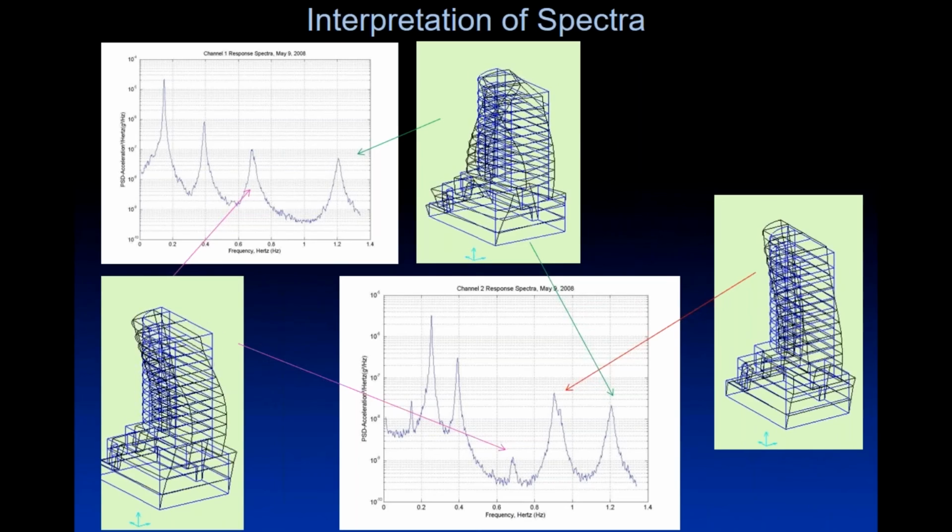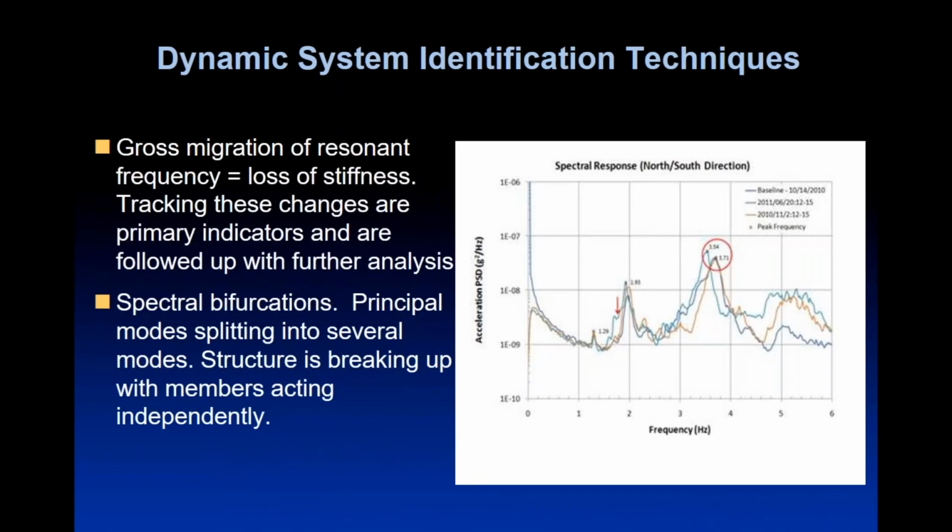We also have here in this bottom spectrum a frequency around 0.9 hertz, which is splitting into two. It's no longer a single peak to that response. Now you may say, oh, that's just random variations, isn't it? You're not reflecting exactly what's going on. Those are random errors in the spectrum. They're not. In this case, the particular response repeated like that for a very long time.